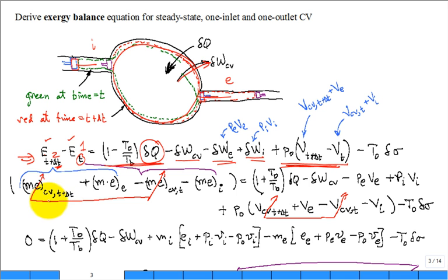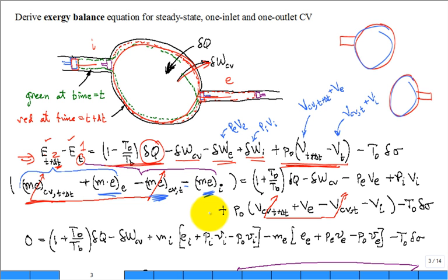All right. So now you expand out this exergy term. You say, well, the system looks like this with a little bit about ready to come in. And at the end, it looks like this with a little bit that went out. And so you say, well, it's what's in the round part plus what went out, minus what was in the round part, minus what comes in. And then the rest of these terms are just copied over. And then we expand those volumes, these two volumes. The CV, the round part, doesn't change with respect to time, so they cancel.